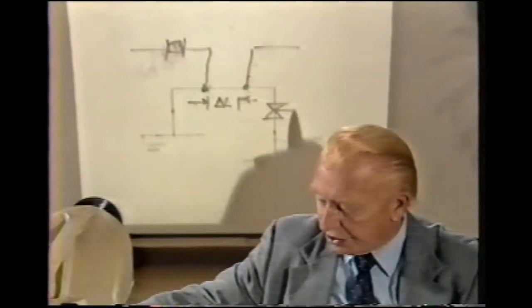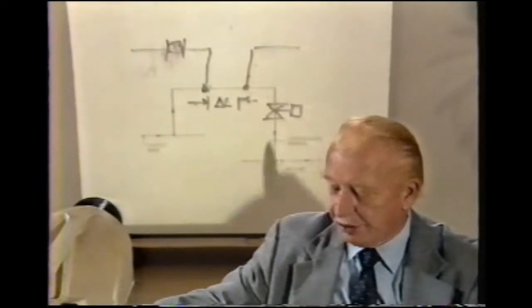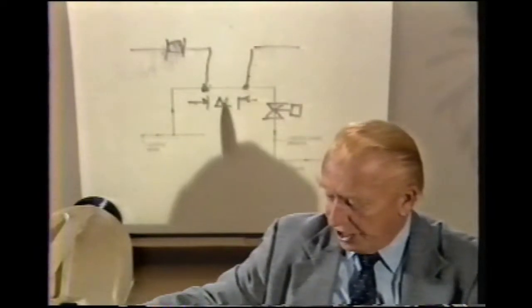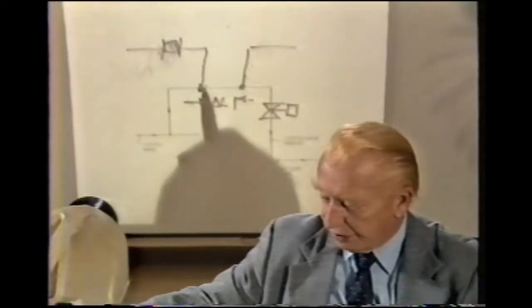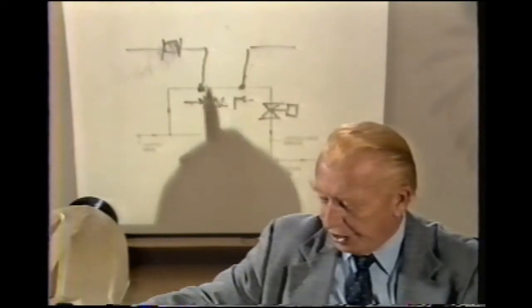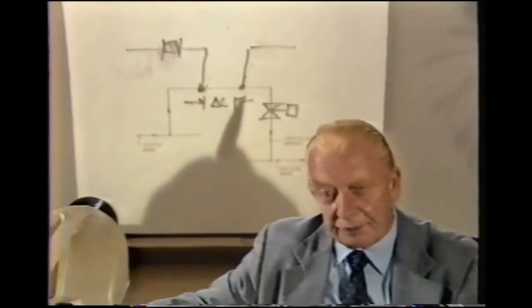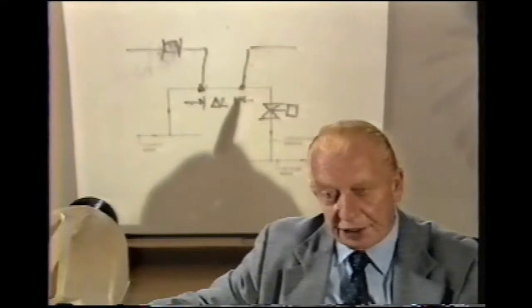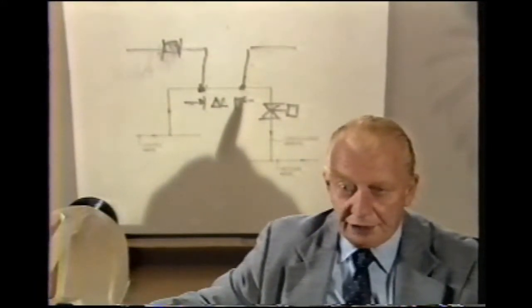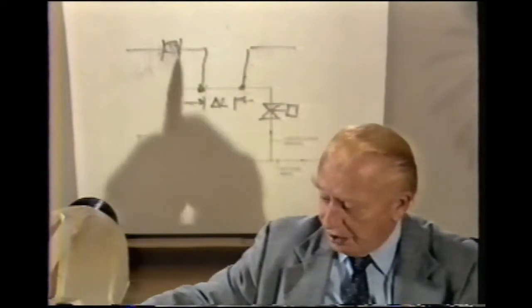Utilizing an application such as this with a control valve in the crossover bridge, we can assess that the length from the supply T to the return T and the length of the common piping can be relatively long relative to the usage of stop-start pumps.